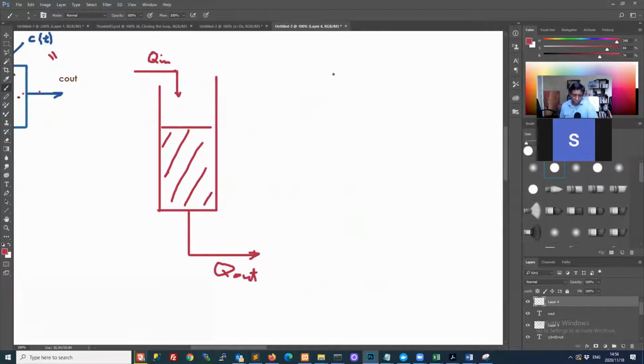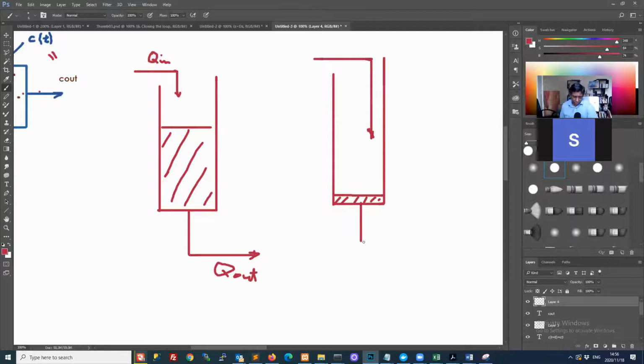And maybe we can draw a slightly different situation here. If you had a low initial volume in that reactor, then your exit stream initially is going to be low. There isn't much driving force to push fluid out here. So you have a low initial exit flow rate and a fixed, not necessarily low, inlet flow rate, so your volume is going to rise.